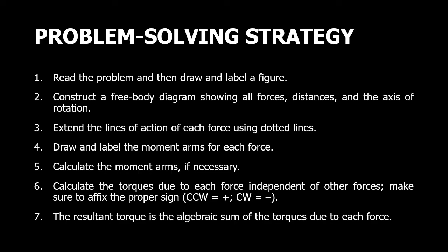Number 3, extend the lines of action of each force using dotted lines for a better free body diagram. Number 4, draw and label the moment arms for each force, since we will be needing moment arms in solving for the torque. Next, calculate the moment arms if necessary.